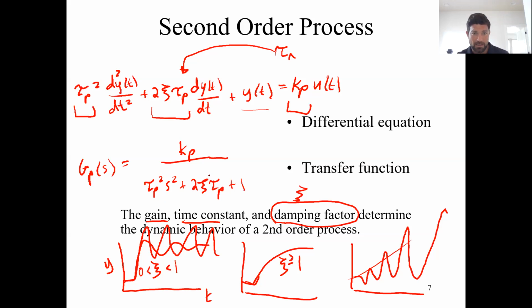Okay, so that's why this is written this way, so that we can calculate the damping factor, and knowledge of the damping factor can tell us about how much oscillation there is in the process. If you calculate the damping factor and show it's like 0.5, you can just say, well, the process has oscillations, I know that, not severe, but it has oscillations.